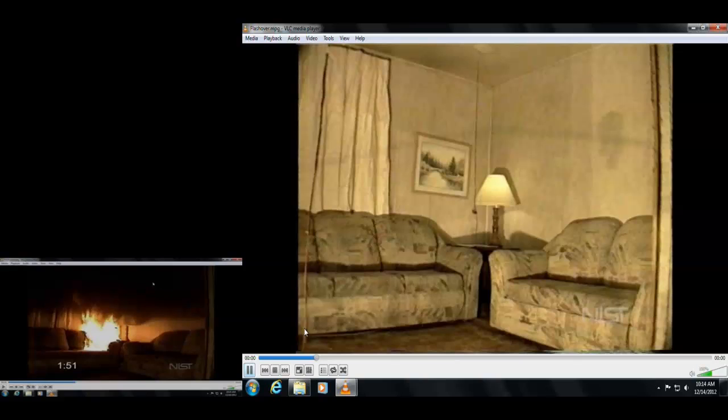Now, as this filling in process takes place, we've talked about this before, but this hot upper layer now is radiating significantly to all portions of this room. And again, it's becoming optically thick so that at some point it would be a reasonable approximation to think about this as a black body at some average temperature. There are several implications to that, one of which is that the pyrolysis process is going to be non-local, so it's no longer anywhere related to what's occurring with this primary fire.